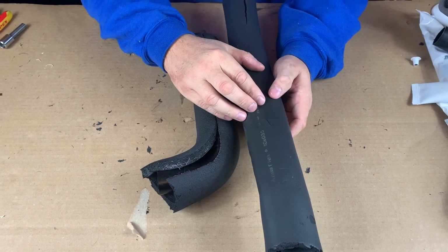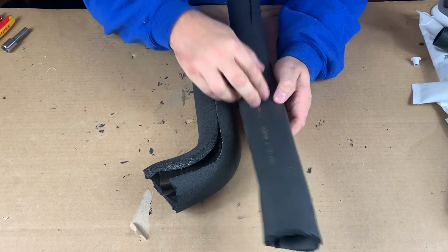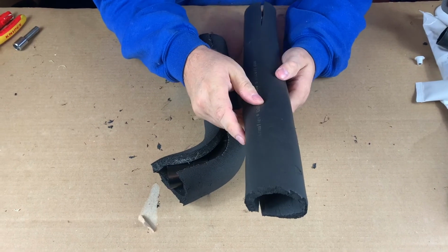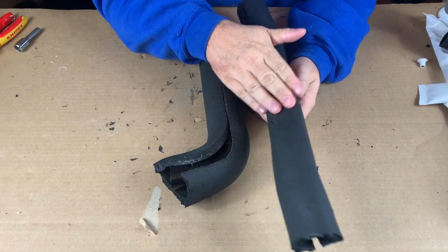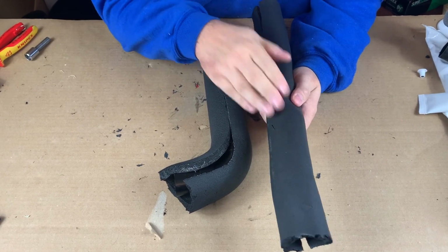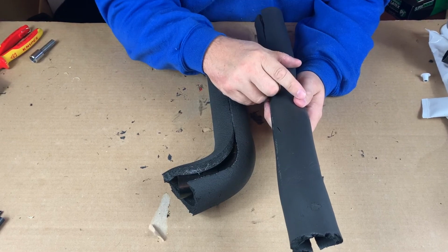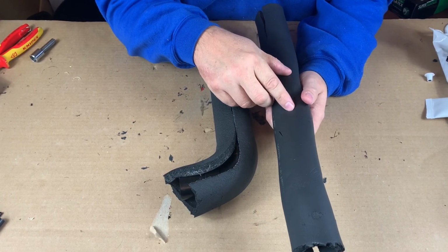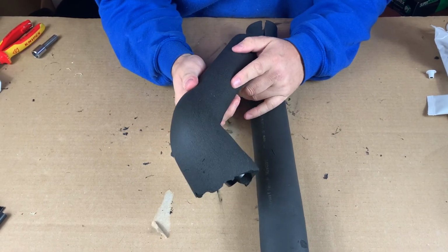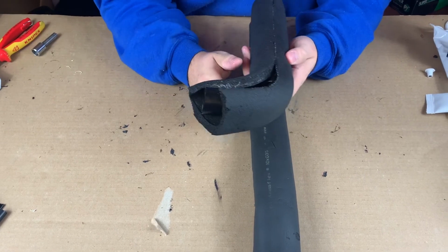So looking at Class O lagging and the reasons why they're stating not to use it unless it's been protected and sealed correctly. First of all, it gets damaged really easily. If you look at the manufacturer's instructions, it must be painted twice, but that's going to cause a problem. If the temperature is too low, you can't do it, and if the moisture is over 85% humidity, you can't use it. Then just the deterioration that we found is if you don't protect it properly, it just turns into a sponge.